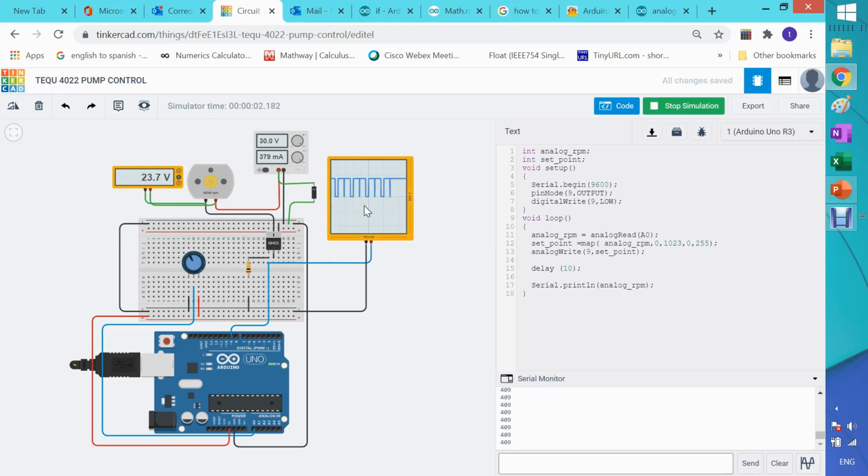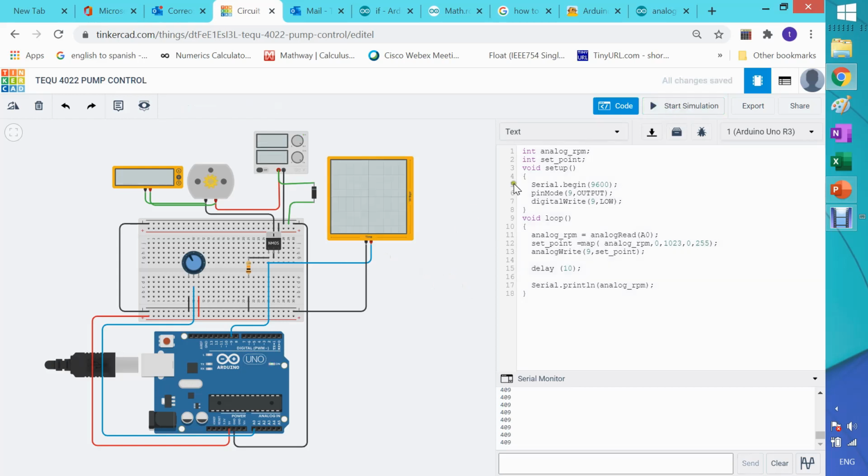So as I was saying, I'd rather do the controlling myself instead of using analogWrite. It worked perfectly. This really is not the way to go. It really gets messed up. Even averaging, sometimes you want to average the input from the analog read on A0, you cannot do that either because, as you can see, everything got really messed up. All right, let's stop here. I think that's more than enough on this subject.